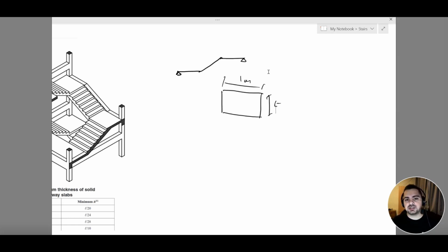However, as structural engineers, we need to simplify our problem as much as possible. If we can avoid drawing a 3D model and resort to a 2D model, we can just go to SAP, draw the 2D model, find the moment applied and the reinforcement required, and this way we simplify our problem by a huge amount. This is something we need to take into consideration.